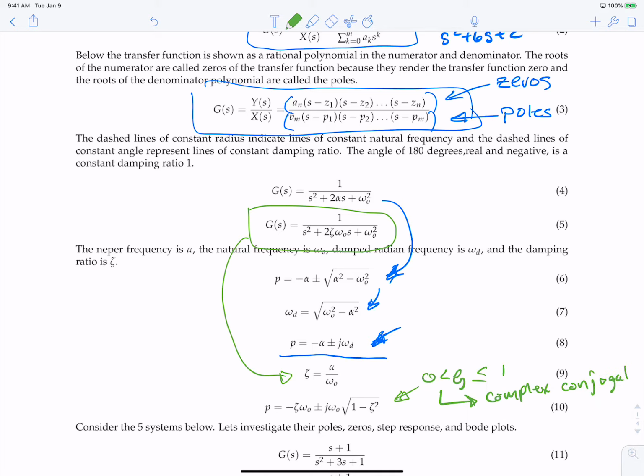All right, this is actually really useful because what this says is if you have a damping ratio of more than 1, then your roots or your poles will be real numbers, which means that you will have an overdamped response, which means there'll be no ringing in the response. Okay, great. That's pretty informational.